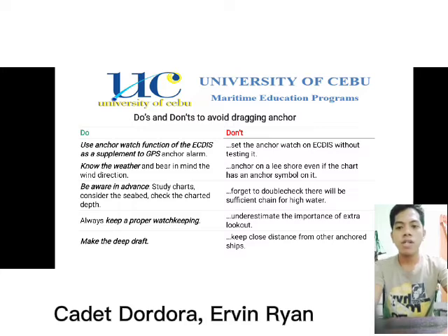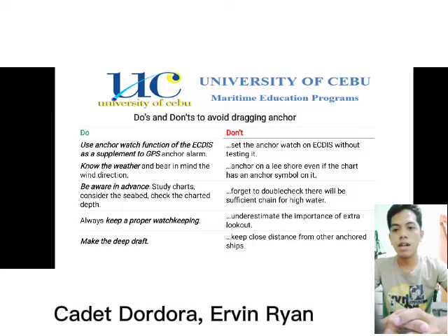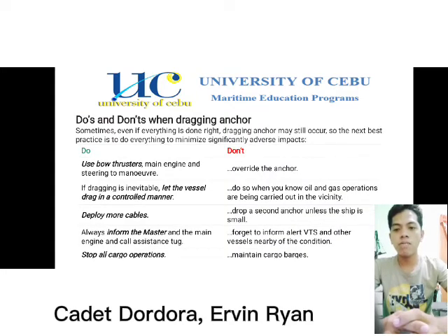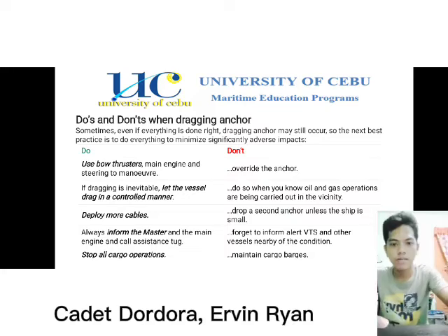Don't: set the anchor watch on your device without testing it. Anchor on a lee shore even if the chart has an anchor symbol on it. Forget to double check there will be sufficient water at high water. And do not forget the importance of extra lookout. Keep your distance from the other anchored ships.